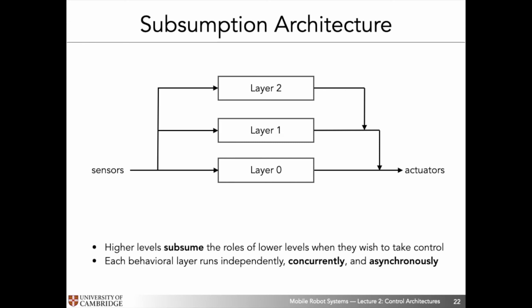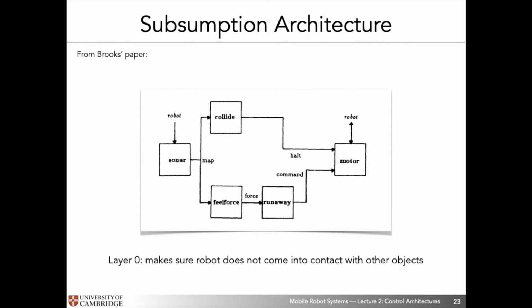So before moving on to our running case study of picking up the trash, I just want to go through one very simple example that shows you how to implement a simple two-layer system for a basic behavior. So what I'm showing you here is layer 0 of a given behavior that, if implemented, allows the robot to simply exist in planar space safely. So the robot won't collide with any obstacles. So how does this layer 0 work?